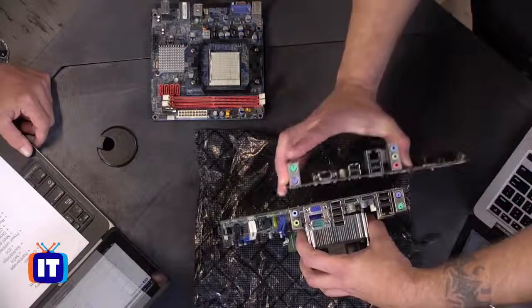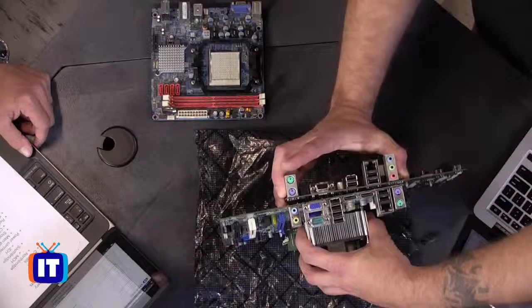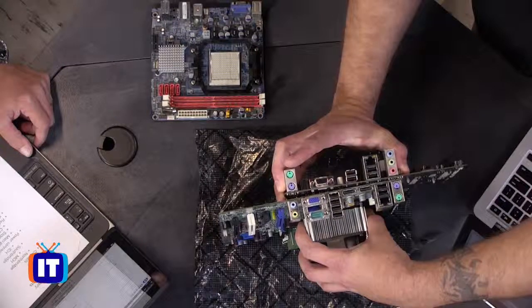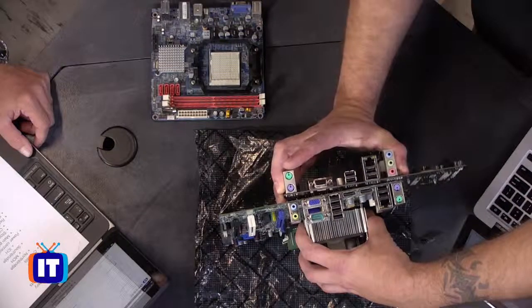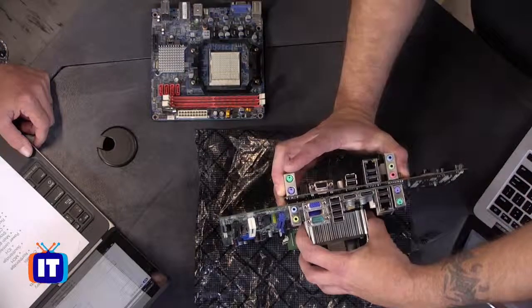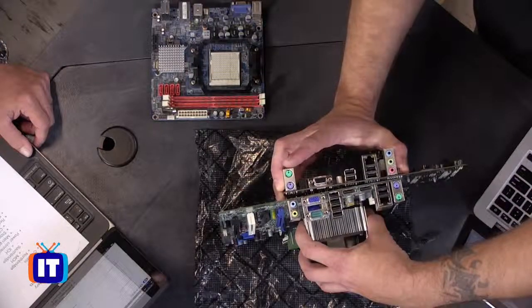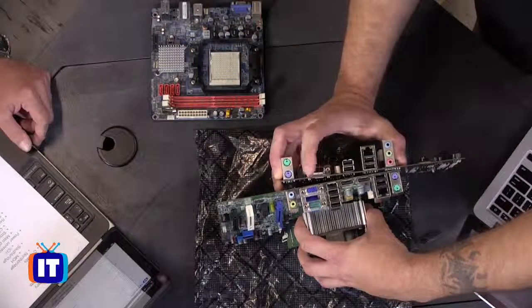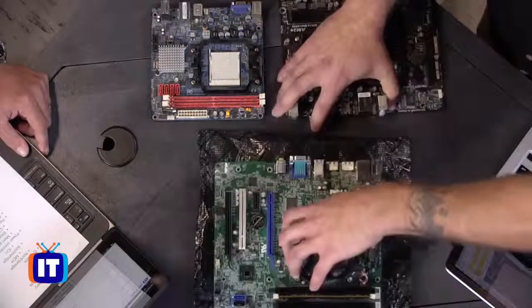And if I put these 2 different boards up here side by side, you'll notice that they're almost the same width, right? Length and height, if you will. And that is because the ATX standard integrates these components in and calls out the rectangular pattern, the dimensions of that rectangle. But what it doesn't call out is what you can put within the rectangle. So it gives the manufacturers flexibility, not saying that you have to have a certain amount of ports here, these ports here, just that we're going to have a rectangular pattern, and you can decide if you want to have these ports here, maybe not even include some of those ports. So it still gives you a standardization.